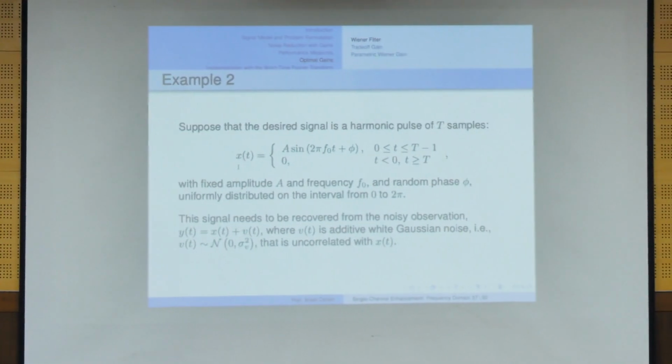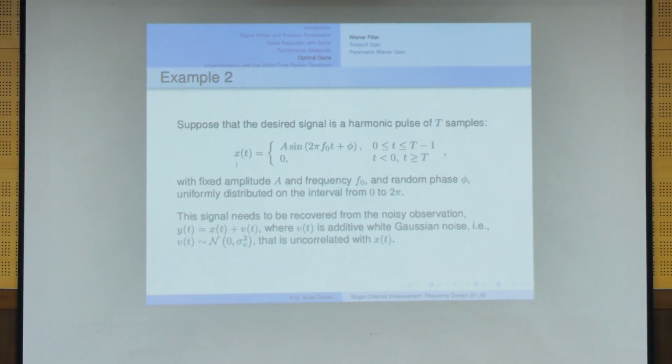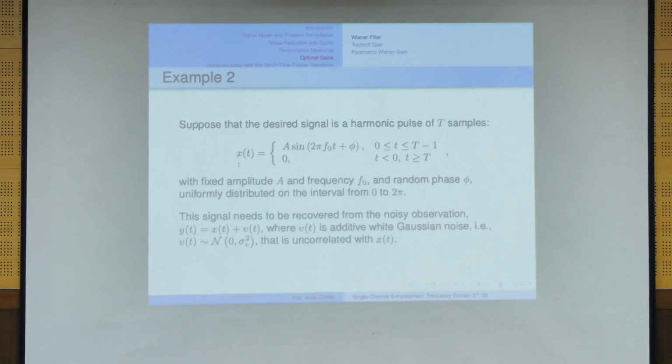So if in the time domain we have multiplication, what do we have in the frequency domain? Sinc, which is the convolution between the Fourier transforms of each. Because we have a certain measurement, we have a sinc.